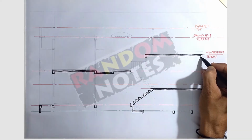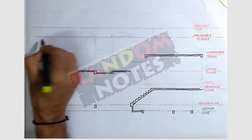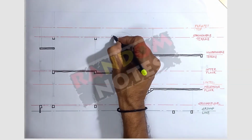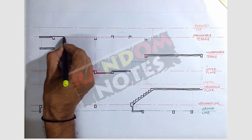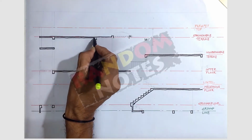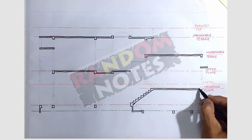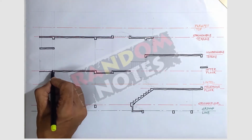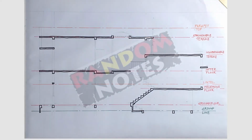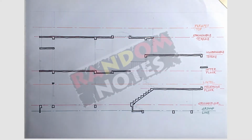Do not miss the smaller slabs like the chhajja or lofts, which may be acting like a lintel for an opening. You may also have inverted beams in some of the parts. At some places, there may be a cantilever projecting from a slab. All openings getting cut by section plane will also have a lintel at the top or a chhajja also acting like a lintel. Now darken the walls which are getting cut by the section plane using a thick line.